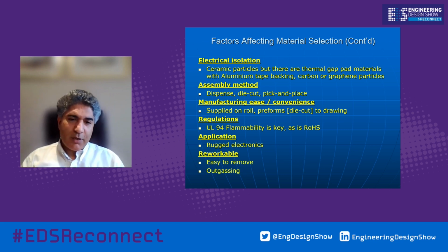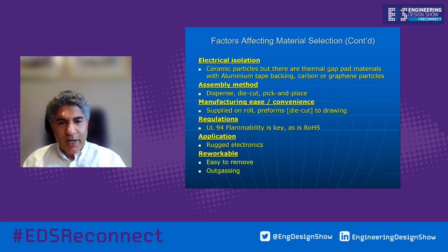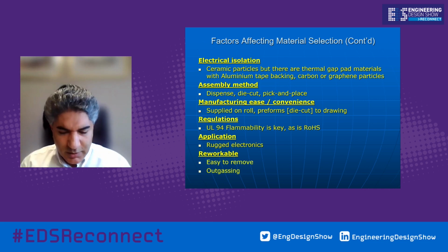Ease of removal, less residue. If it's a cure-in-place material, room temperature cure, it's quite challenging to remove it, or a phase change material, it could be challenging to remove apart from the heat sink and substrate. Outgassing typically could be relevant for the rework element of it, or if you've got lasers or lenses, you want to avoid silicone leaching, like a smear element of it.